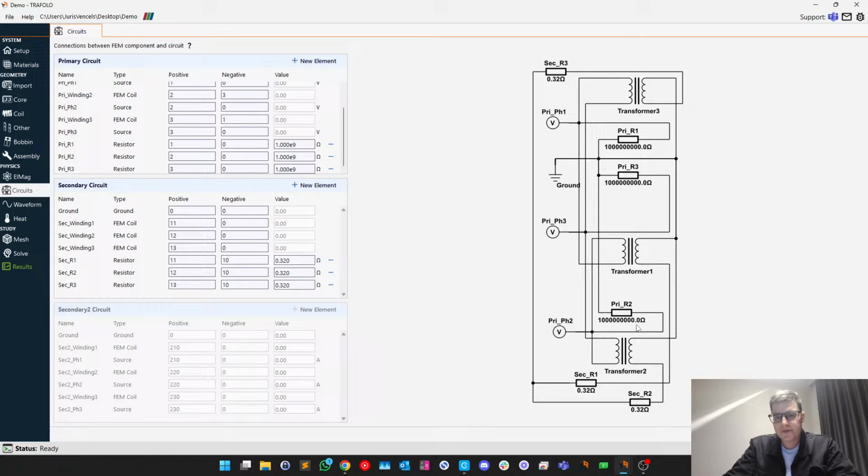Very large resistances, but only for numerical reasons we had better put them here. Otherwise, simulation software sometimes is so accurate and at the same time has machine precision that it causes convergence issues if you don't add those resistances. So pay attention to that.